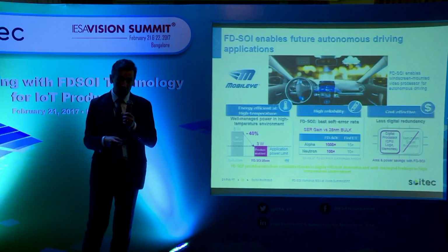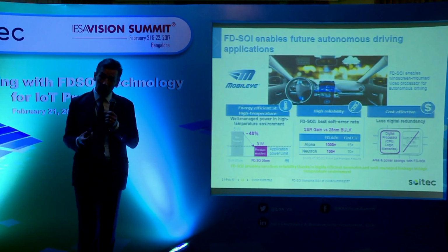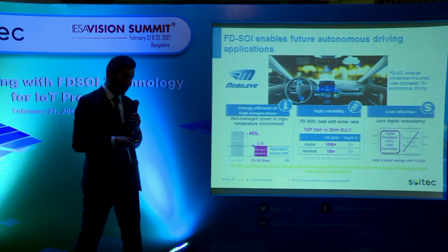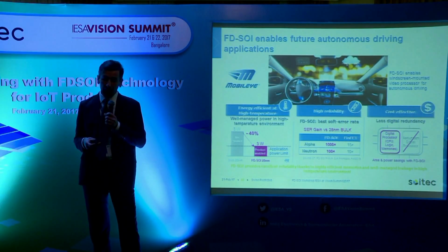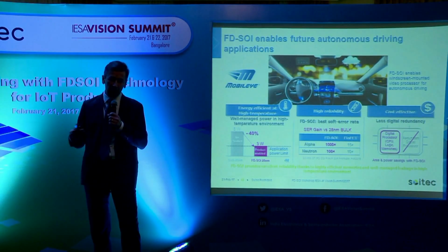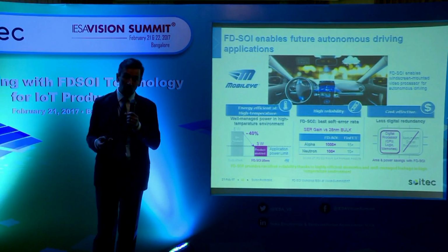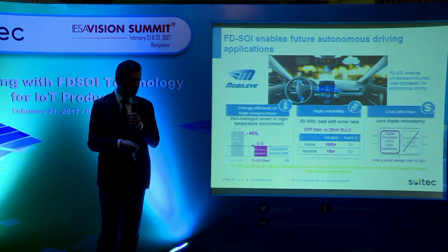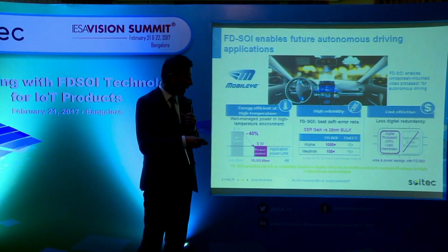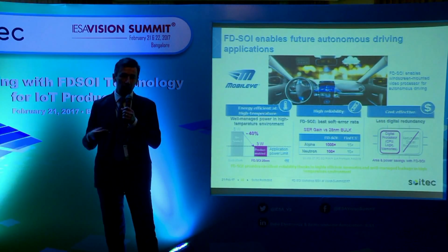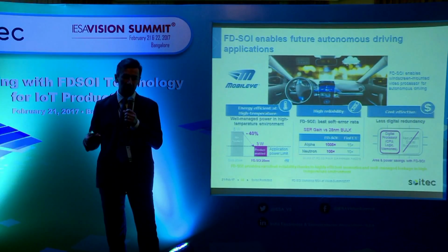The second one I mentioned already is soft error. Because of all different types of impact from radiation, different types of radiation coming from the engine, from the electrical engine or other sources, today in the design, often you need to design having an additional chip or additional capability just to prevent a soft error in the calculation.